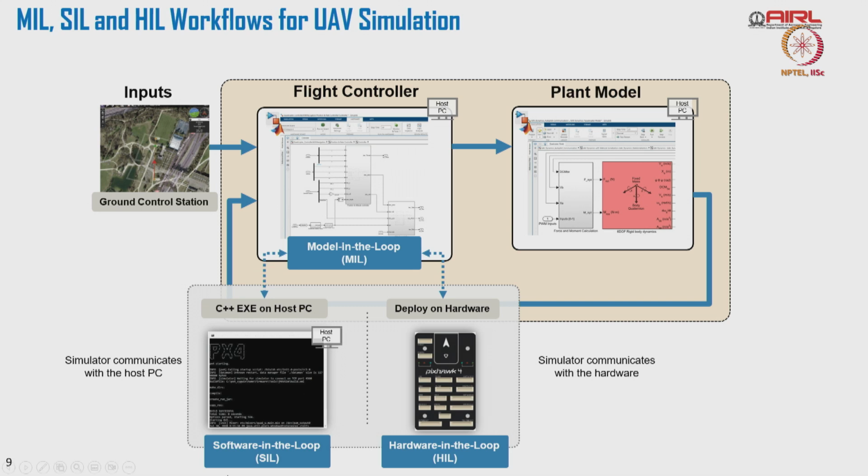Now you also need a software in the loop where you validate everything, convert all these models into an exe file, and then pass it on and check whether I'm able to run it in real time, right? This workflow is very important to validate the deployability of the algorithms we are building in this particular course, right? Your flight control law, or even the navigation algorithm, whatever you are going to study later, we need to know how we can deploy them in real time.